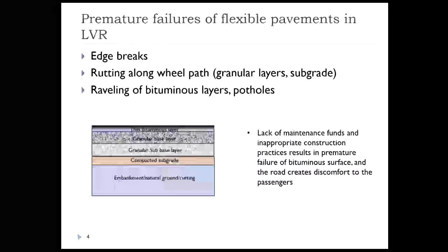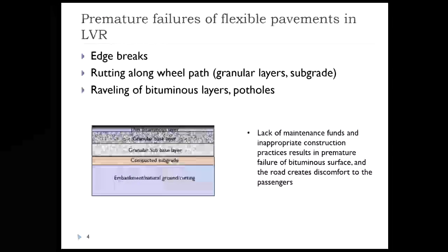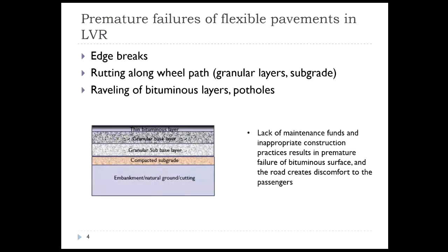It can also happen that the traffic on that particular road grows exorbitantly larger because of some unforeseen reason, say sand mining activity or any other quarrying activity taking place, and you find a large volume of heavy vehicles utilizing the road. As a result, you may find this permanent deformation or longitudinal depressions in the wheel path.